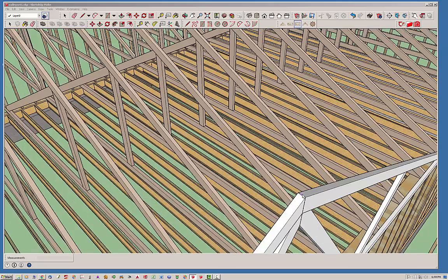So wherever I put this next point, the valley set truss will position its first truss out here, basically whatever the spacing is. So I'll demonstrate. Let's go ahead and select the middle of the peak of that final truss, and then the final point you want to select here on the peak, and that just defines the direction of the valley truss set.